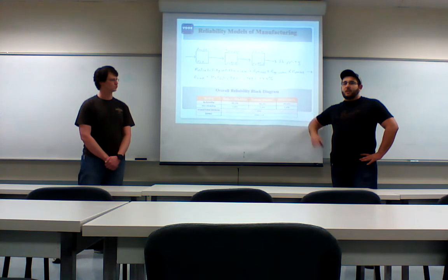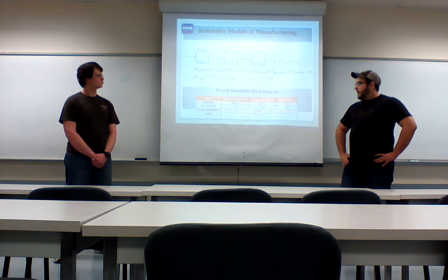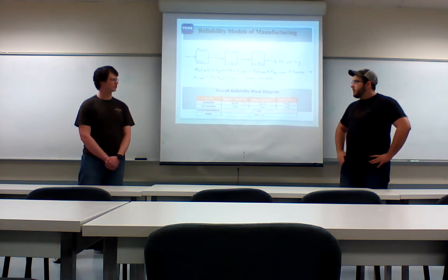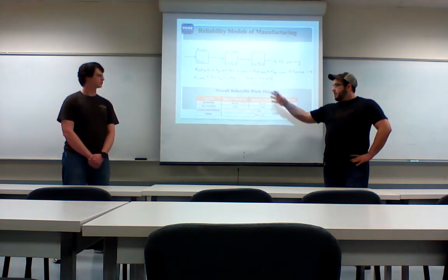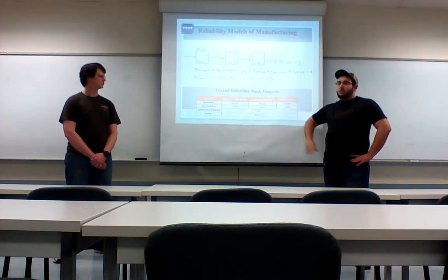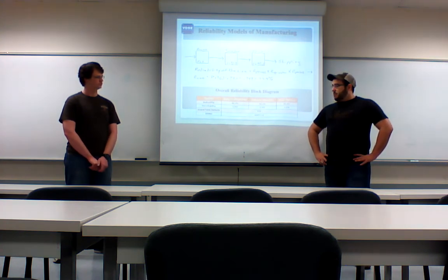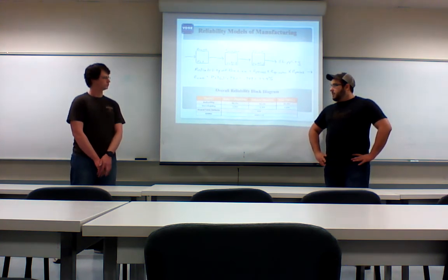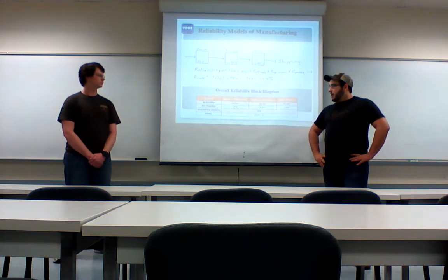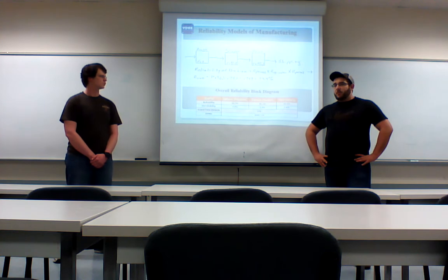Therefore, we use the series reliability calculation in order to calculate the total reliability of our system, which we calculated to be 94.4%. The defects received by the weigh station and the visual inspection station are where the defects are kicked out. Those reliabilities are respectively 96.2% for the machine and 98.2% for the visual inspection, and we also have a defects per million opportunities of 30,857.